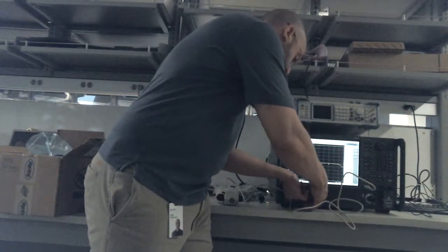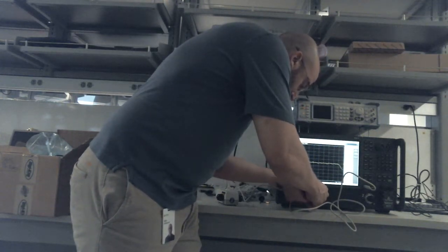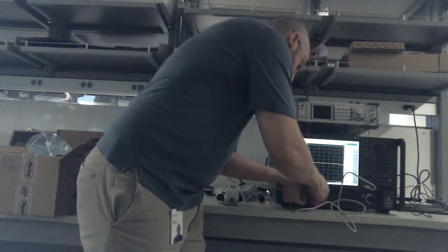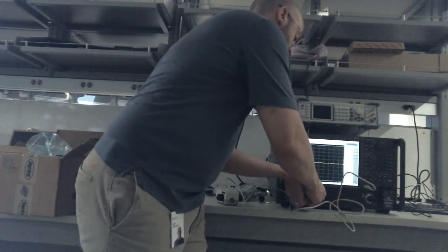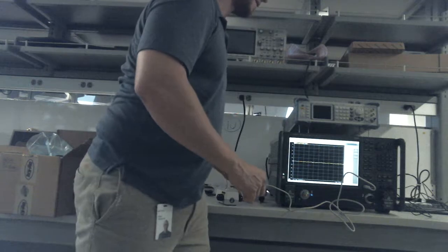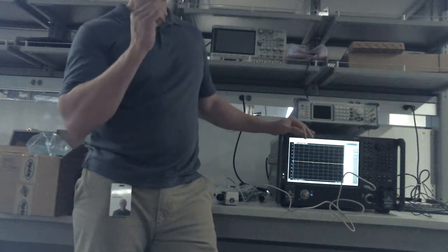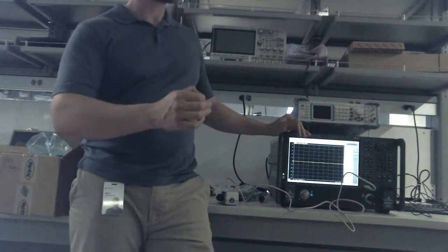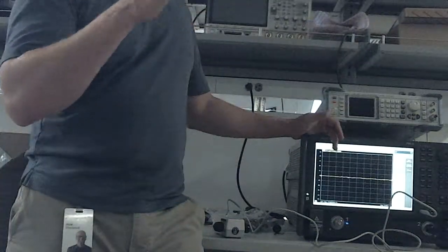So the main thing that you want to do when you're doing your measurements is to think about what you're going to connect to. You may end up connecting to BNC, but the first thing that you do before you even connect it to the network analyzer is visually inspect your connectors, right? A lot of the times I go into some labs, especially undergrad labs, connectors will be lying on the ground, sometimes they fall, you might get damaged, right?